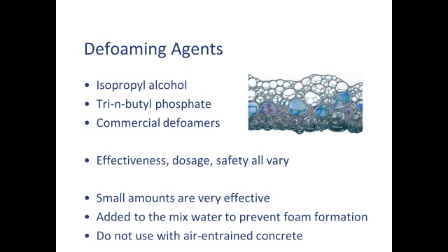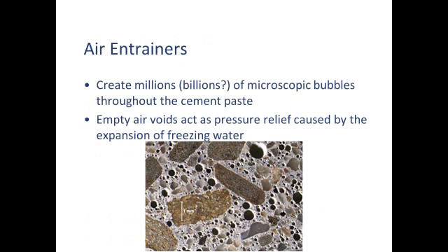I tend to try to use as little as possible because we don't really know what the effect on the concrete is. We're using so little, it's doubtful that it has any real effect on the concrete. And if you're going to be using air-entrained concrete, which I'll talk about in a minute, don't use a defoamer, because the purpose of air-entraining is to put bubbles and foam in the concrete. So they kind of work at odds to each other.